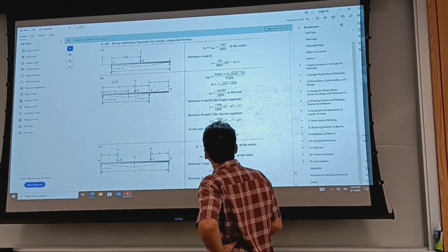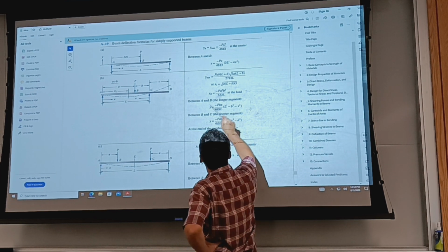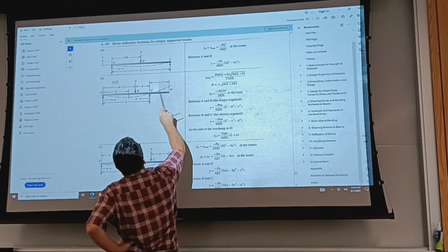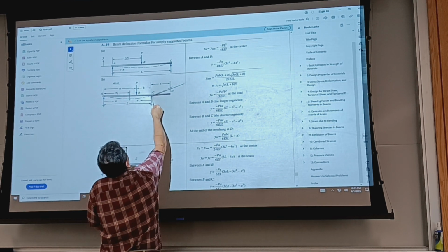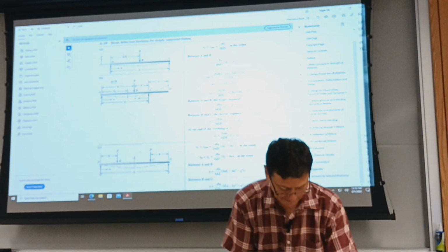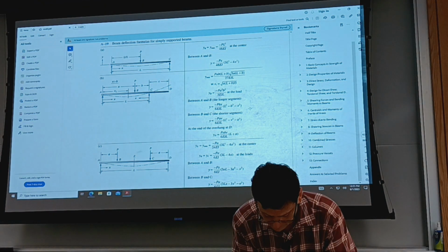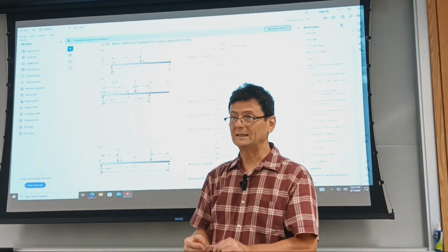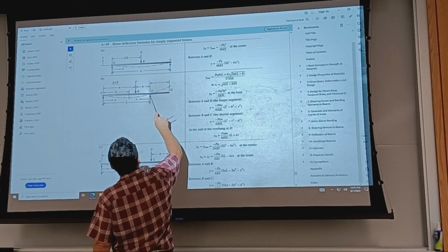And then it says, do we have an equation between C and D? So between A and B, actually this is trivial. If it looks curved, it's not correct. Between C and D, this is just a straight line, and it does not seem to be one. Does it make sense? Because if I have a beam and I load it here, from the support to the free end there's no loading, and the beam just remains straight, following the slope evaluated at point C.